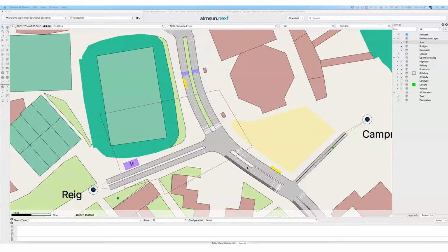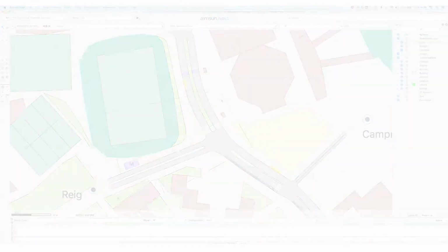It can be a good idea to disable editing of some of the sublayers, so as not to make any undesired changes. In that case, right-click on the desired layer and disable Allow Object Editing. This will prevent you from making any undesired changes to the polygon.